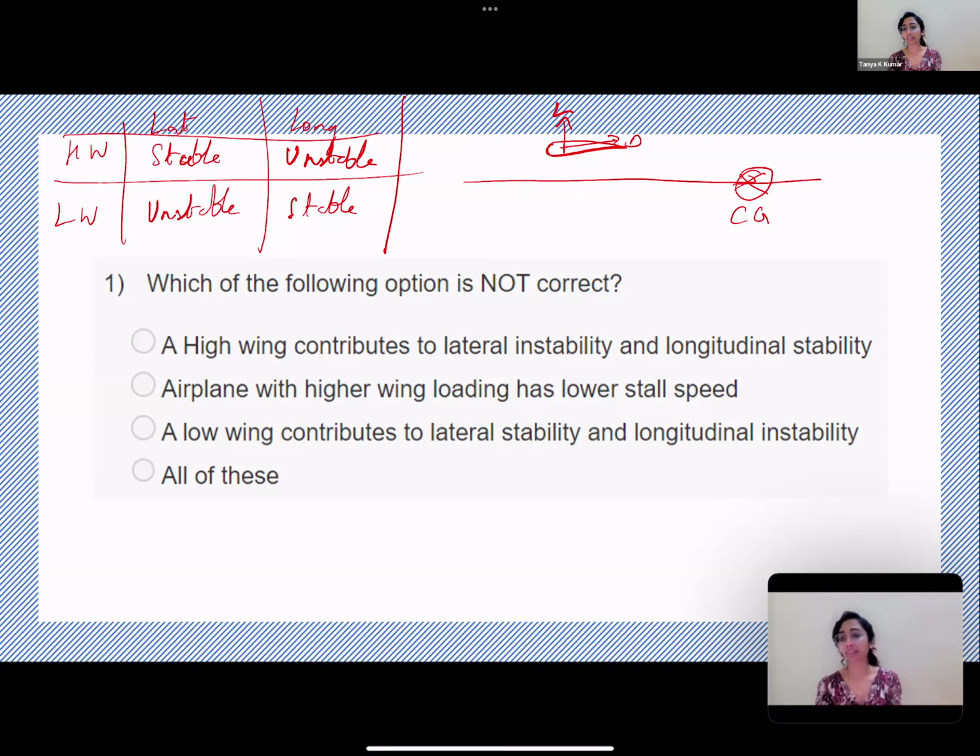Okay, fine. So if your aircraft is subjected to a gust and your wing is providing a lift, it provides a destabilizing moment about CG. Correct, it creates pitching moment. So what in this high wing configuration contributes towards further instability?